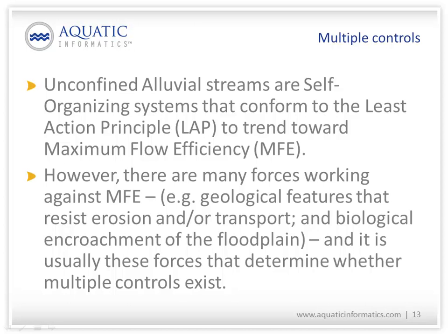One of the things that I always find very satisfying about my work in hydrometry is how well our very simple hydraulic relation, our rating equation, works for so many streams all over the world, over such a wide range of stage for very different streams. This is because unconfined alluvial streams are self-organizing systems that conform to the least action principle, and they trend toward the maximum flow efficiency.